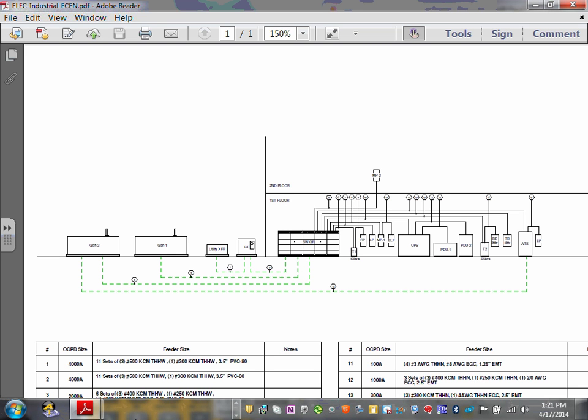Bigger branch circuits, bigger feeders, voltage drop. So we're going to put them typically in the center of the building. If you have a multi-story building, it's nice to have a panel or panels for every story, so it feeds the receptacles and lights if your building is big.